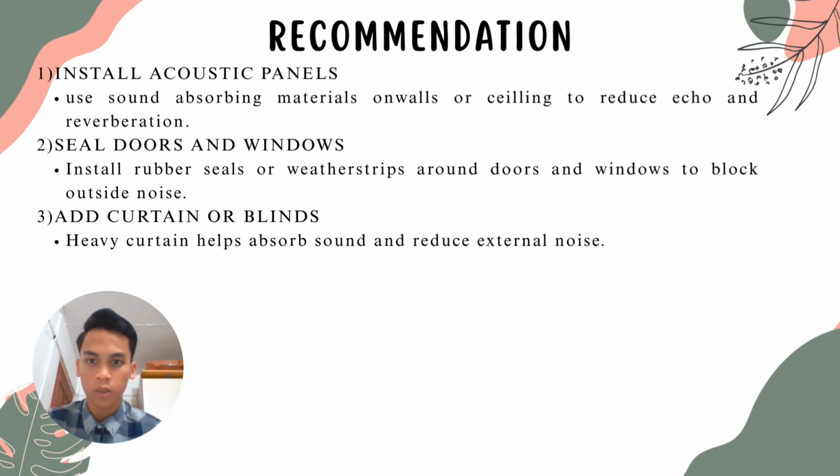The third recommendation is that we need to add curtains or blinds. This is because heavy curtains help absorb sound and reduce external noise. So these are the recommendations that we need to follow to reduce the noise and make the students in the classroom more comfortable and more focused to study.